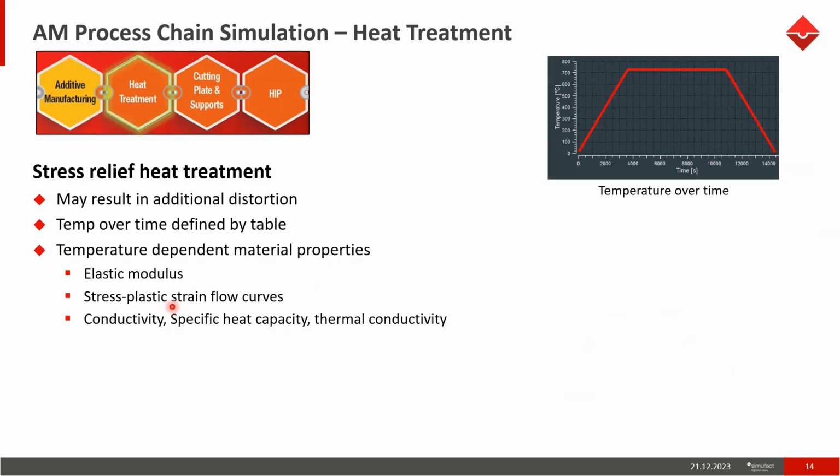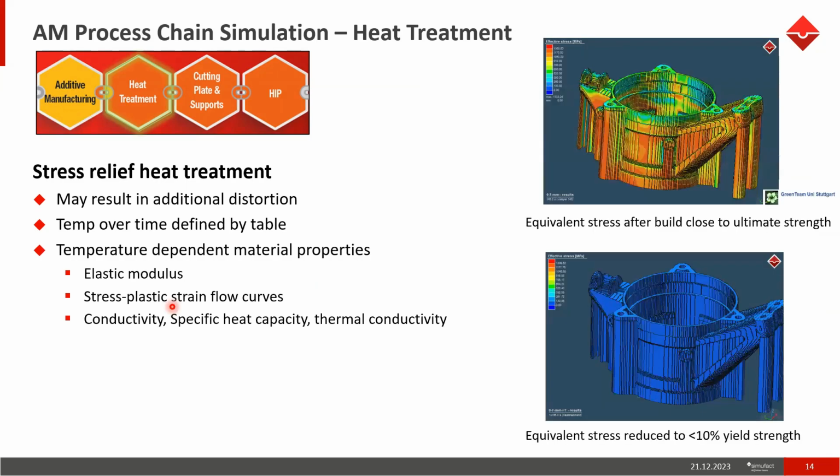And heat treatment can be done. Stress relief heat treatment. Normally, they do the heat treatment to relieve your residual stresses. So you can see the part after it is manufactured, a lot of stresses can be built, and after you relieve your stresses, you can get the part which is free of your residual stresses, which is ready for the subsequent process like support removal and things like that, so that it will not cause any kind of damage to the part due to residual stresses.